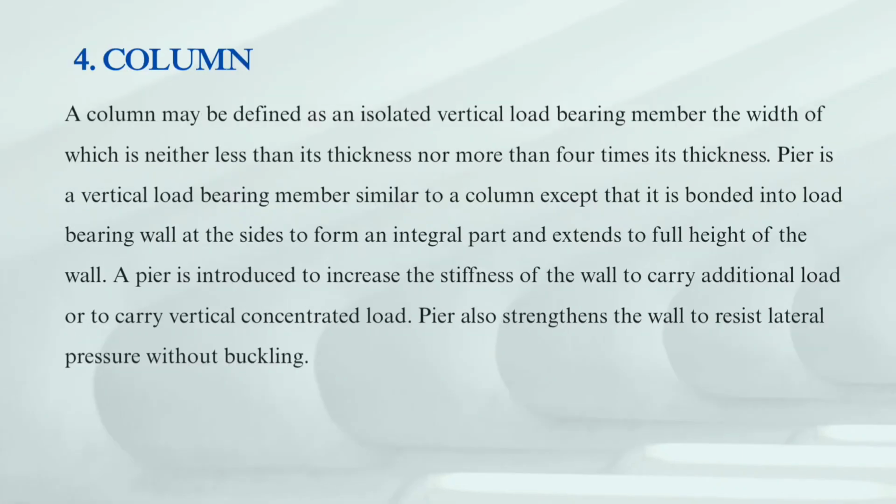Now the next component part is column. A column may be defined as an isolated vertical load-bearing member, the width of which is neither less than its thickness nor more than 4 times its thickness.